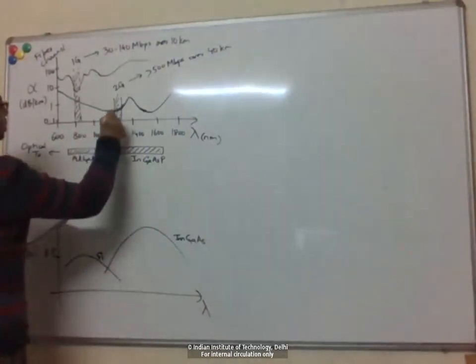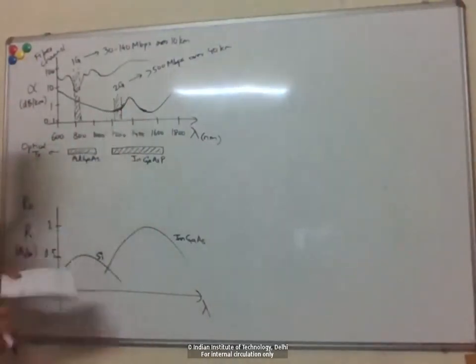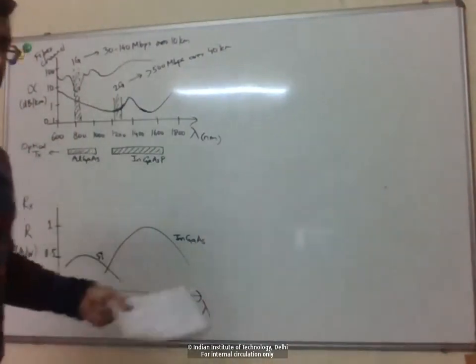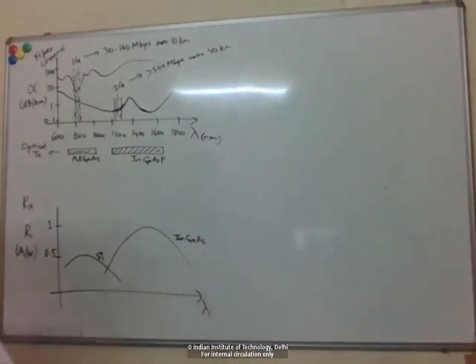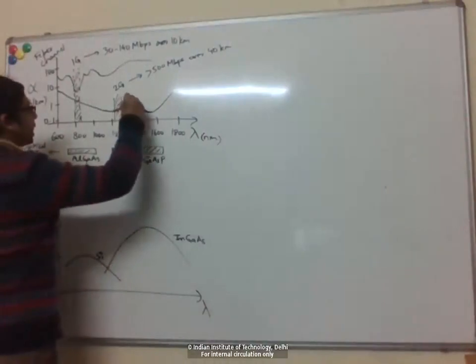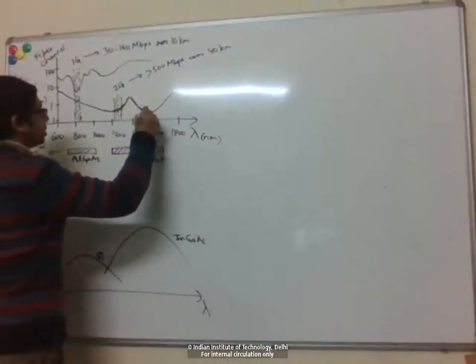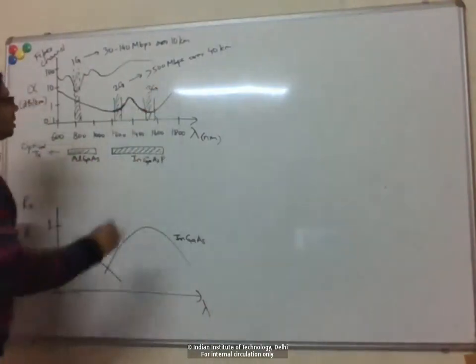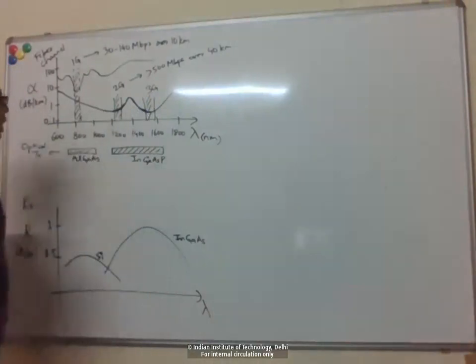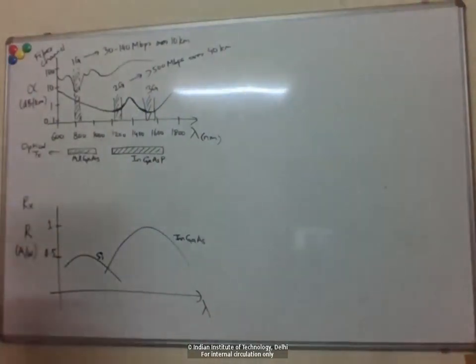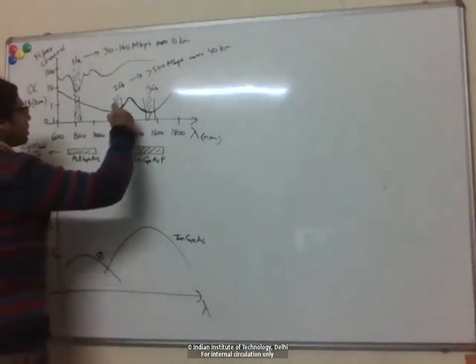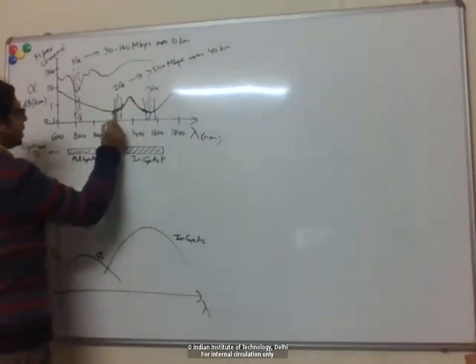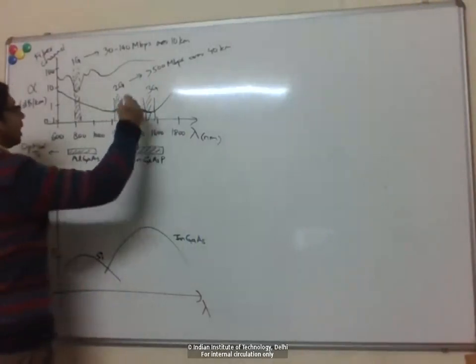And then as people wanted to expand the optical networks further and further, going towards longer distances, people found out that actually the minimum loss, around 1550 here, is even slightly lower than at 1300, right? And that's partly because you have this peak coming here, which increases the loss here.